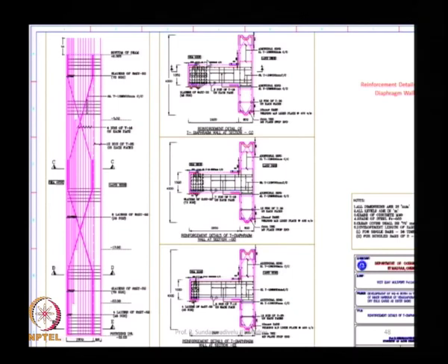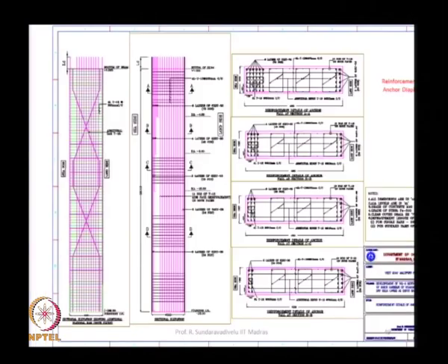Actually this reinforcement, this diaphragm wall is not same as what we have given here. I will skip this, it is slightly changed. So, this is all right. This is on the sea side, we put so much of reinforcement here. The spacing between the bars in this side as well as this side should be more than 100 millimeter. We have to provide some compressive bars also to tie these shear stirrups. Whenever you are designing, you have to design for both bending and shear, and you have to provide some more shear stirrups also. What is called as a